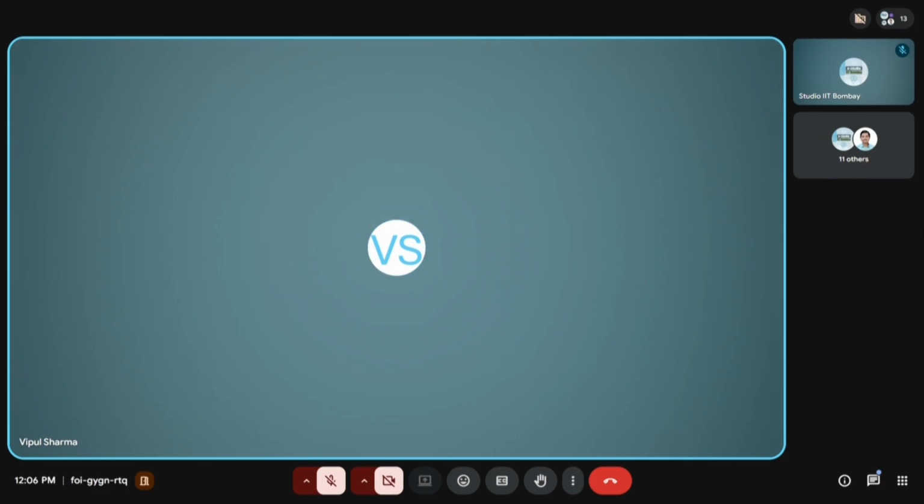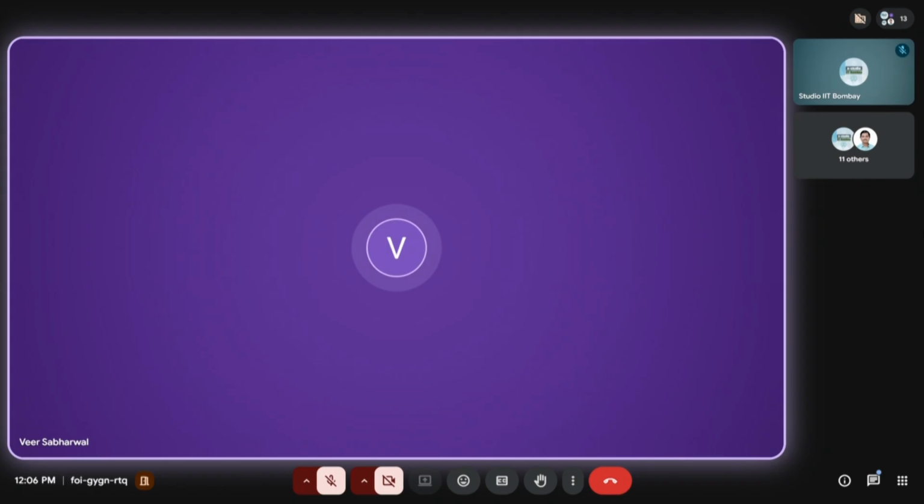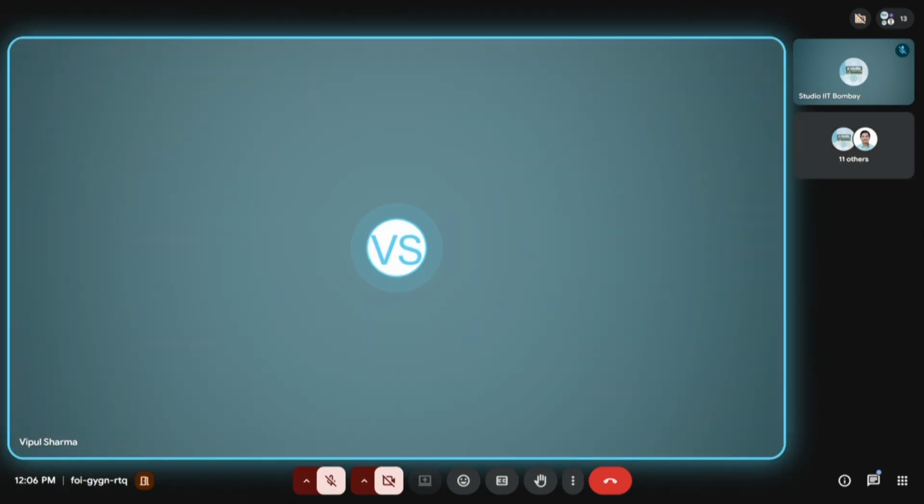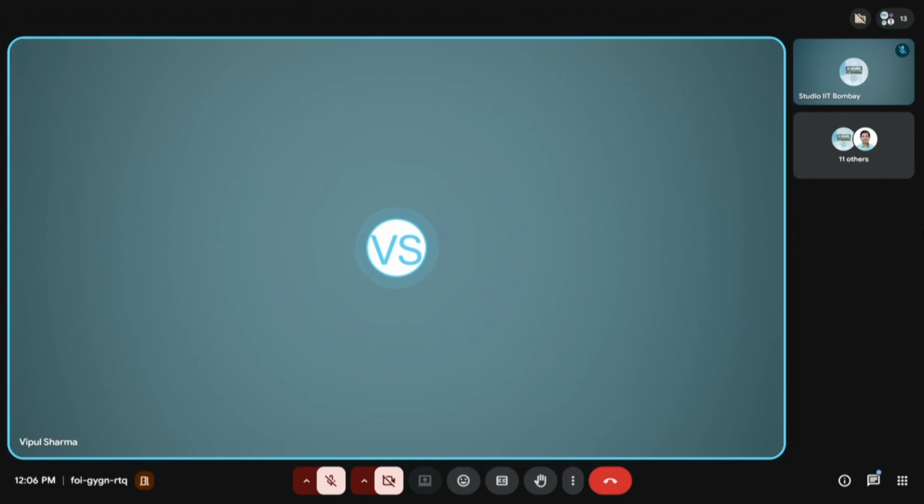Any other questions? Sir, I also wanted to ask about electrical rule check. Like, what is that? Can you just explain? So ERC rule checks are a bit complex. There are some electrical rules, like if there are latch up effects or some other effects which are basically inbuilt into your PDK. For certain circuit configurations, these are not mandatory, but these are required for checking the robustness of a circuit. Those kind of effects might not affect your circuit's performance. So those are called electrical rule check.